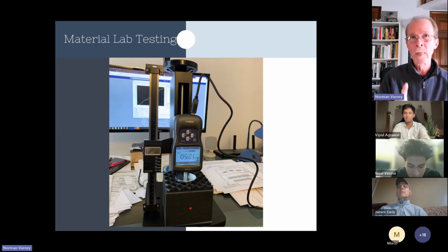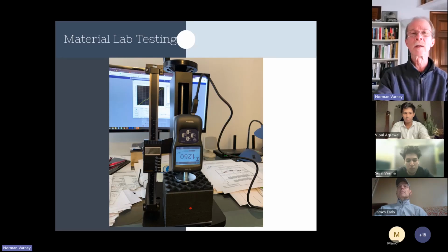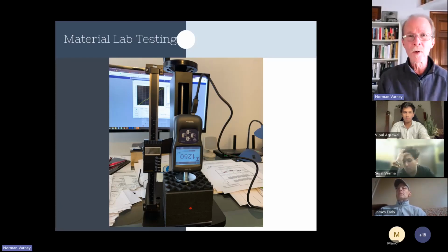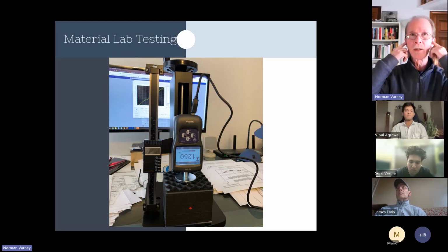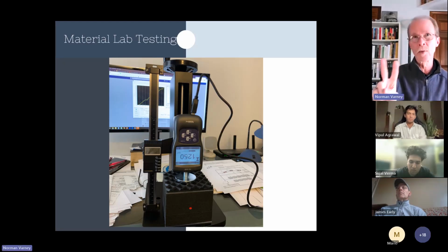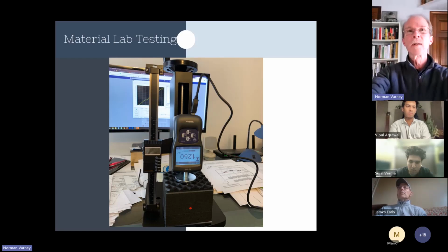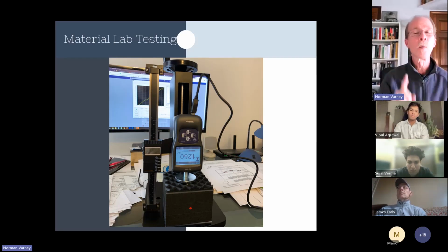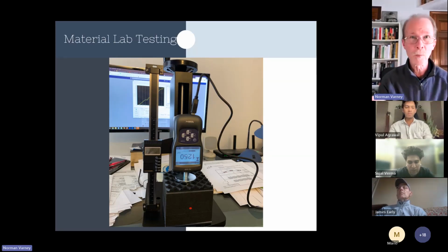The first one: the denser the material, the medium, the faster and the further sound energy travels through it. So when you're playing your speaker, the first thing that you experience is structure borne. The first arrival is structure borne via the floor to your chair, to your butt, via bone conduction to your ear. The second arrival is airborne from the loudspeaker to your ear. That's the one that we want, the only one that we want.